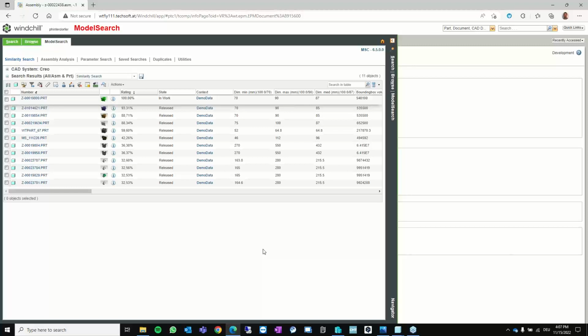We call it combined search, as it combines geometric searches with external attributes. As you can see, the result list looks similar to before. The models are once more listed using decreasing similarity weighting, but the only difference is that only released models are available in the result dialog right now. This functionality, once more, isn't only restricted to Windchill. You can also add it to Creo Parametric.